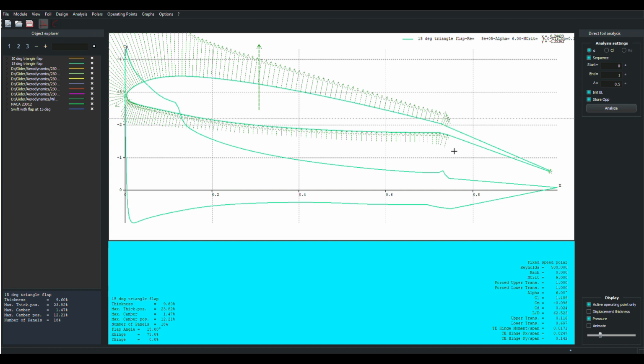And of course, it just says that as you give the flap portion some thickness up front, a more airfoil-like shape, it's more effective at generating nose-down pitching moment. But as we know, that's a problem in terms of adverse pressure gradient for the flow that's slowing up and trying to get around the corner. 15 degrees here appears to be about the maximum deflection without having a problem. And interestingly enough, that's about the same as what the Swift is right now.